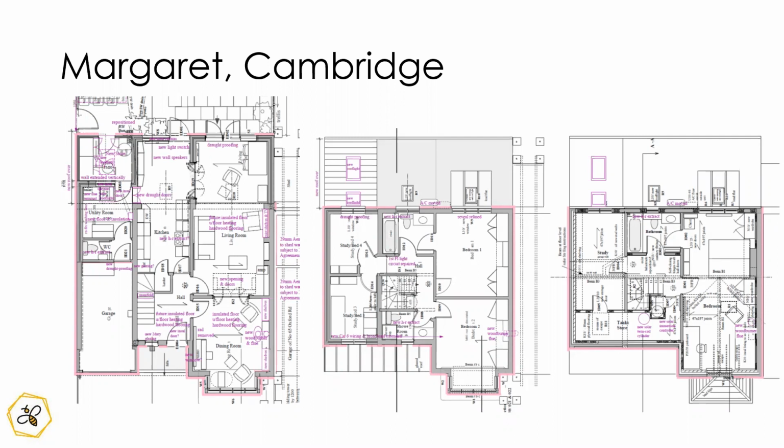Maybe an option would be a split system, and you could replace the existing gas boiler with a hydro box, and then you run refrigerant between that and the outdoor unit, and some of those run up to 50 meters between the two. Yes. So a hydro box inside. Yes. If I could put that in the loft.